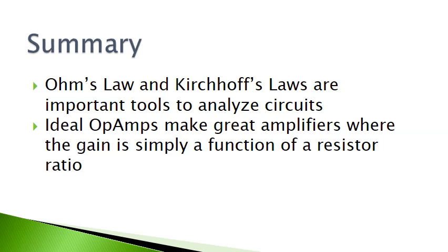We can choose R2 and R1 within reason. So the ideal assumptions still have to apply, but we can choose that ratio to create an amplifier of almost any gain.